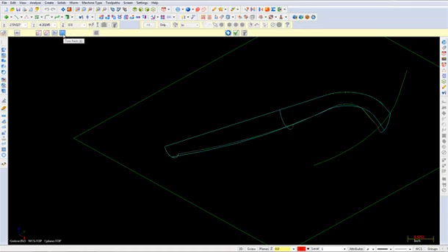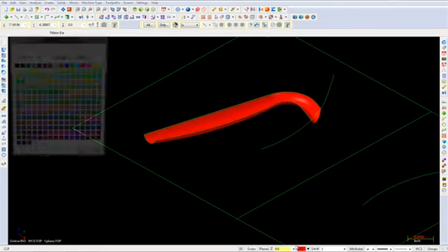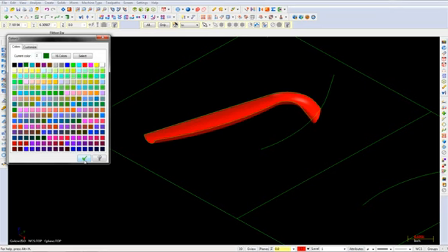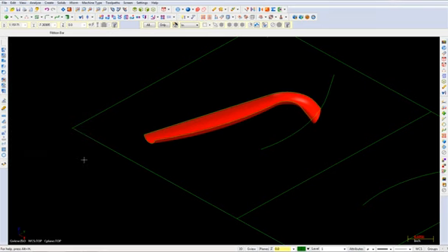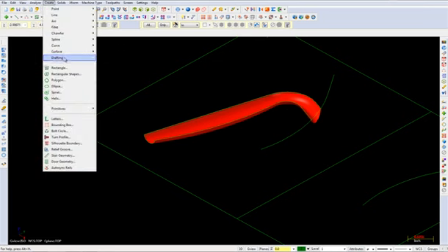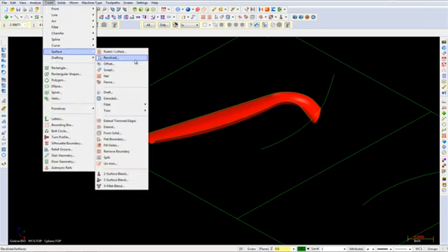In the ribbon bar, enable Two Rails. Then select the OK button to exit this command. Left click on Color and change the main color to green number 2. Select the OK button. Then click on Create, Surface, and choose Revolved.